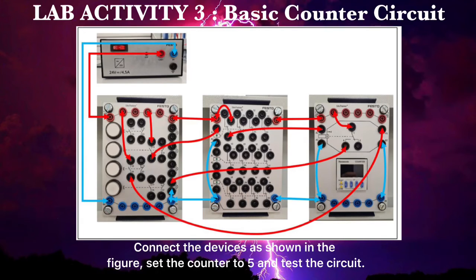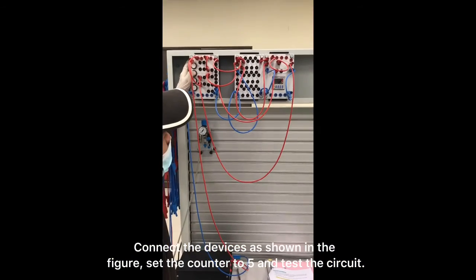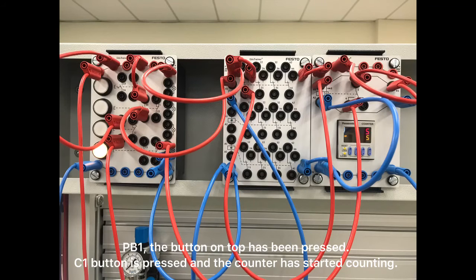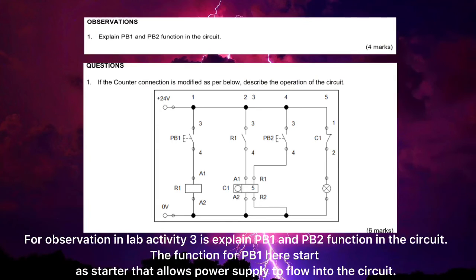Lab Activity 3, Basic Counter Circuit. Connect the device as shown in the figure, set the counter to 5 and test the circuit. PB1, the button on top, has been pressed. The C1 button is pressed and the counter has started counting. After the counter reaches the set count, which is 5, the bulb will light up. PB2 has been pressed. The whole counter will reset back to 0, and the bulb lights off.